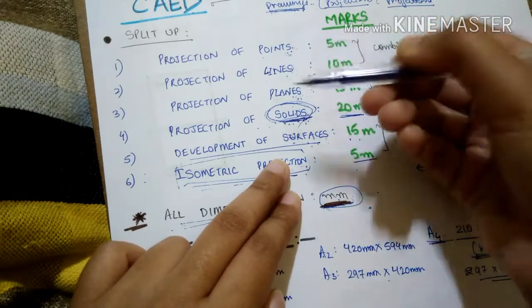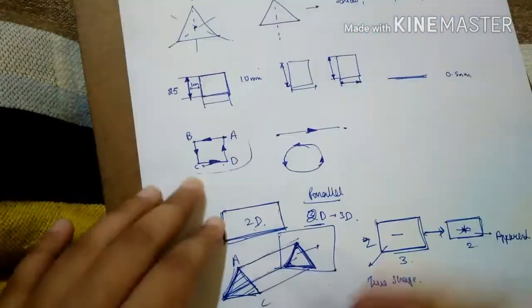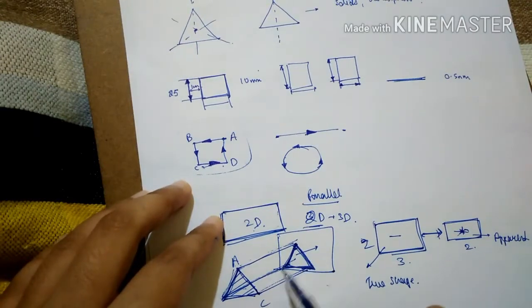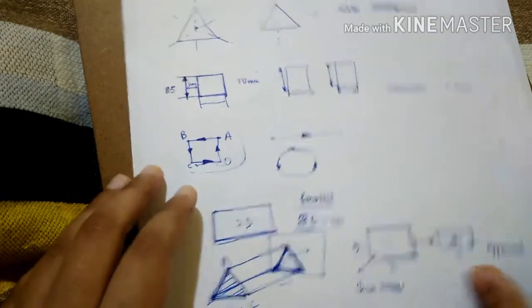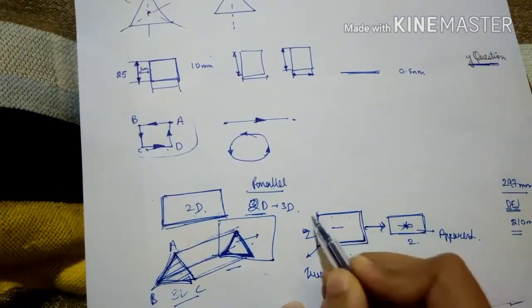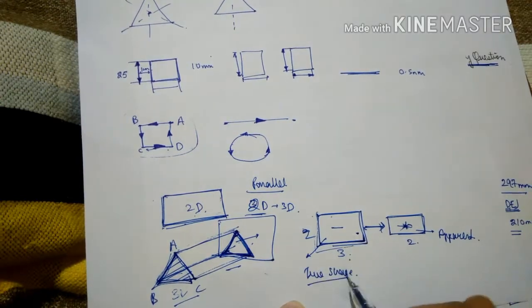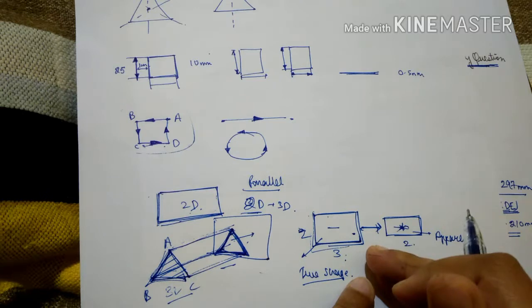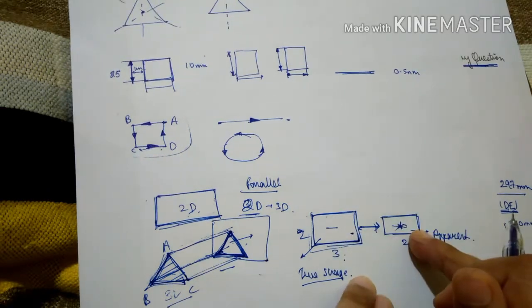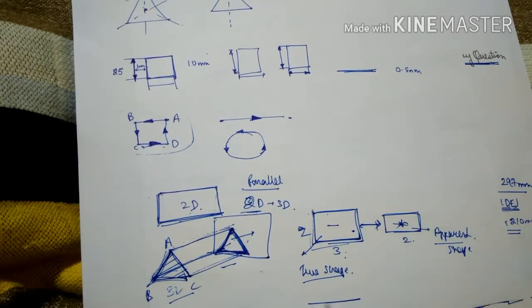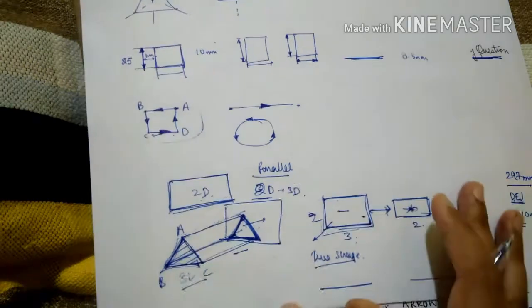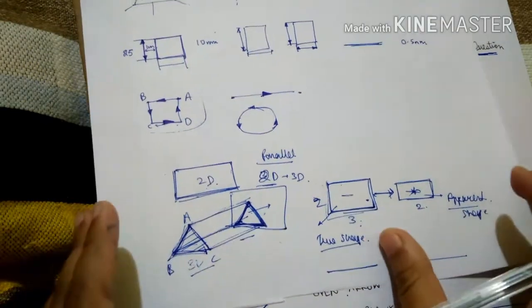What is orthographic projection? It is parallel line projection. If you have an object, you project the lines parallelly, and when you join the points, you get the image that is the true shape because it is of the same size as the object. So that image is a 2D representation of this 3D object. Now what is true shape? If I have an object, the initial size of the object is the true shape, and when the given conditions are applied to it, the image we get after drawing it is the apparent shape. Or you have apparent line thickness, true line thickness. You have many such possibilities.